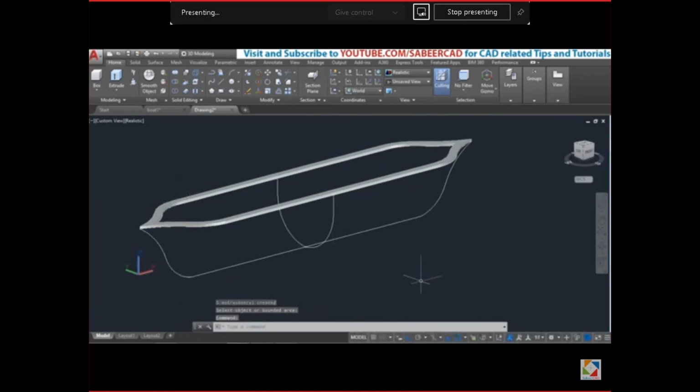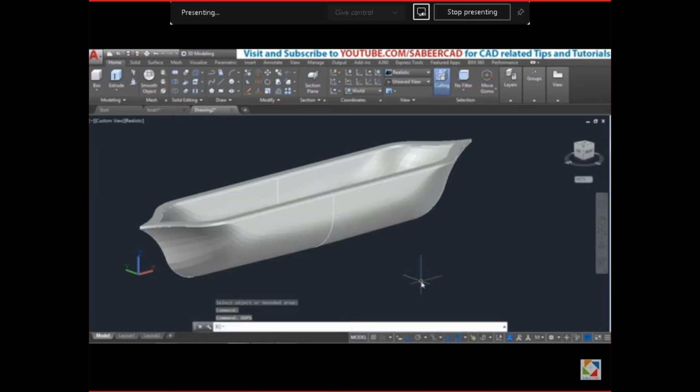Next, I would like to get those erased meshes back. So you can give the oops command for that, because you know oops restores the most recently erased set of objects. But if you erase a set of objects with the intention to get these objects back using the oops command, you should not erase any other objects while you work.